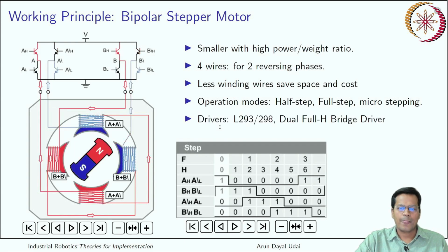Yes, the possible drivers for this are L293 and L298. That is a dual full H bridge driver, which you may know through your embedded knowledge, or hobby electronics people use it. There are industrial drivers also for this.